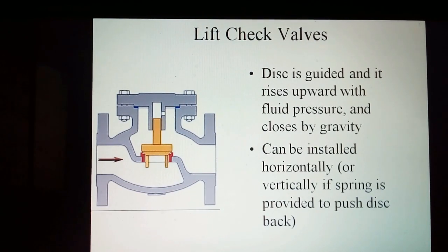Lift check valve. The disc is guided and it rises upward with fluid pressure and closes by gravity. It can be installed horizontally or vertically, with springs provided to push the disc back.